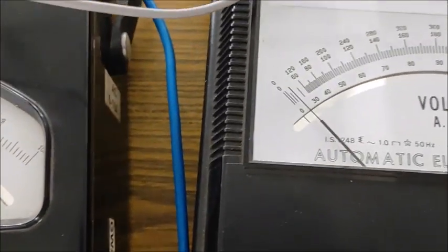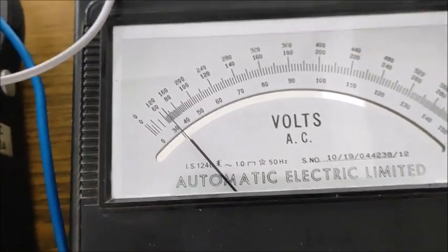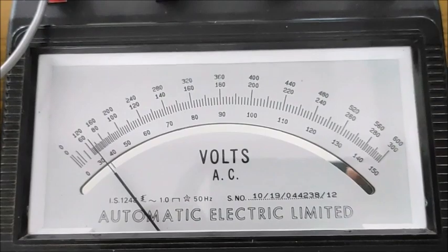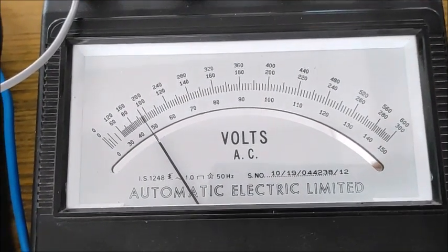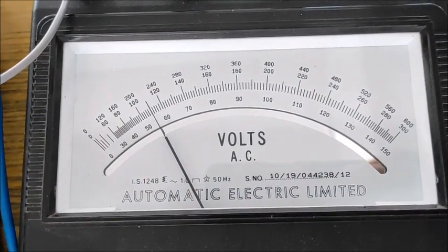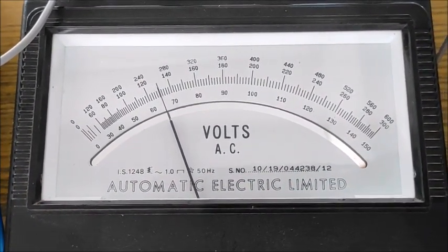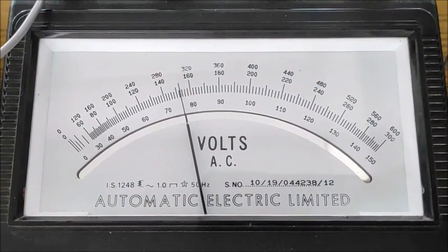So you can see here that I am now applying the voltage by rotating the knob of the auto transformer, that is the rotary switch, and you can observe here that this voltmeter gradually increases. You have to apply the voltage of 400 volts. So how to read the voltmeter, I will explain you now.